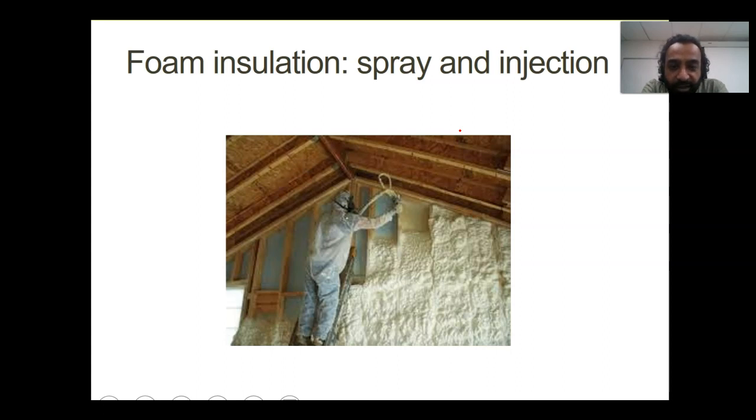And as you can see, the guy is wearing a space suit here because this material is very sticky. If you've ever worked with those little foam cans, it's very annoying. It's really hard to control. So as you can see here, the guy is filling up those cavities with foam, and you have to cut it and shave it to make it even because you cannot control how the foam will expand. They are very rigid. They insulate a lot of noise. They're a good option, but again, it's really messy to work with.